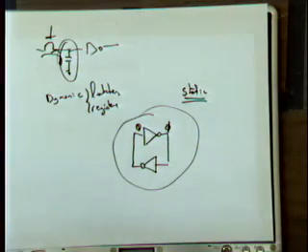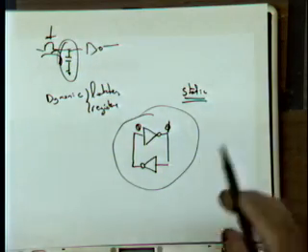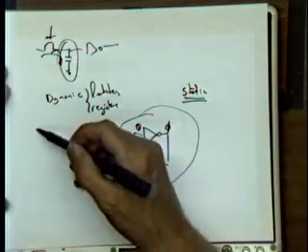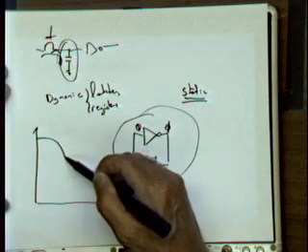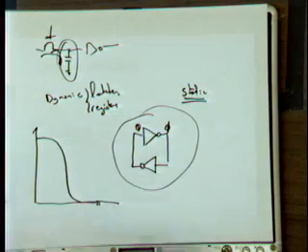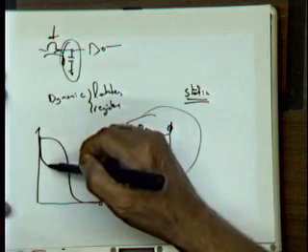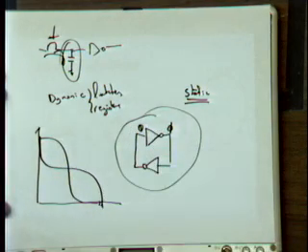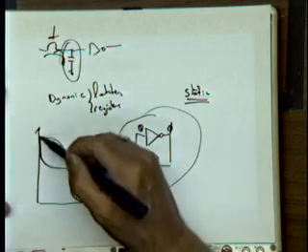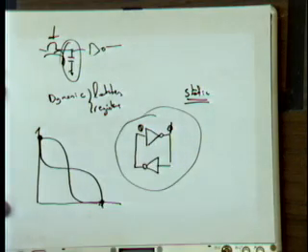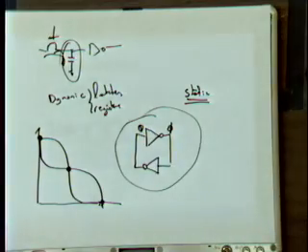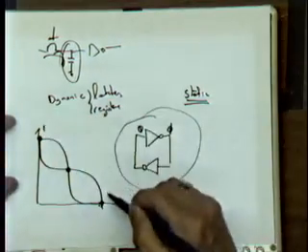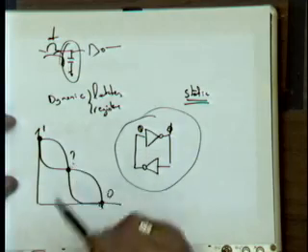This idea is a very interesting thing. I'll show you this in the next lecture: every inverter has a voltage transfer characteristic, something like this. This is inverter 1. If I now connect inverter 2 back to back, you can see that I have a number of stable operation points. Actually, I have 3 stable operation points: a 1, a 0, and something we don't like.